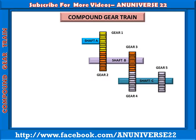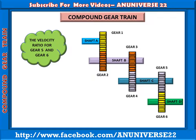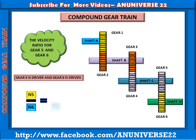And here is another gear that is mounted on shaft C, that is gear 5, and this is shaft D on which gear 6 is mounted, and gear 5 and gear 6 are matching with each other for transmitting the motion from shaft C to shaft D. The velocity ratio for gear 5 and 6, here gear 5 is driver and gear 6 is driven. Then it is N5 upon N6 equal to T6 upon T5. N5 is the speed of gear 5, N6 the speed of gear 6, T6 the number of teeth on gear 6 and T5 the number of teeth on gear 5. This is equation number 3.